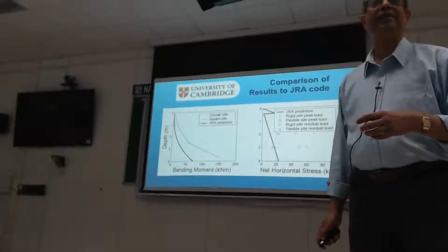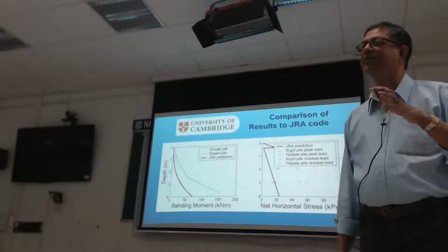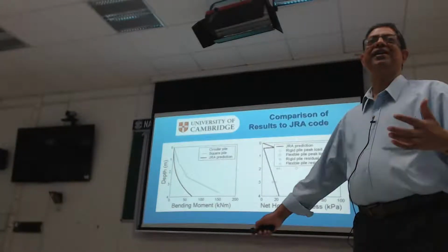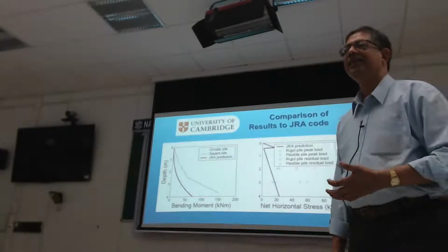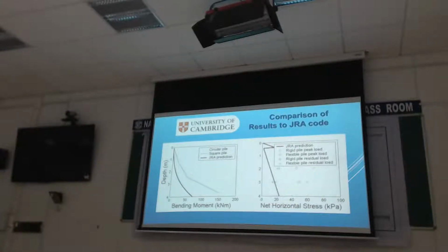2.2, 2.3. What did we say at the beginning? For static design, you'd consider a factor of safety of about 2, 2.5 for piles. So it's going to fail. No wonder so many bridges and pile foundations in Japan have failed, because JRA was considered to be the best, most up-to-date code following the Kobe earthquake. Now they have revised their code. They basically multiplied all their factors by 2.5, almost directly from this graph.